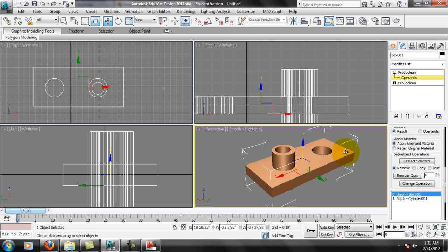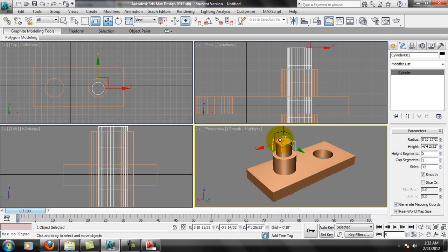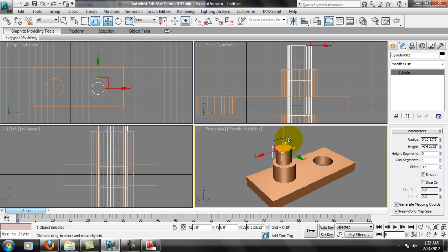See the base. I have the base selected there, so that's not going to work. So I can extract anything with the base, obviously. If I need that guy back, I can take it out. Notice that undoes that. If you use a Boolean, you don't really have that capability. So Pro Booleans are better to use in this situation.